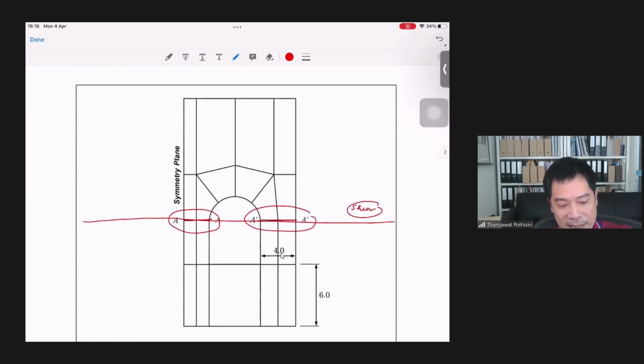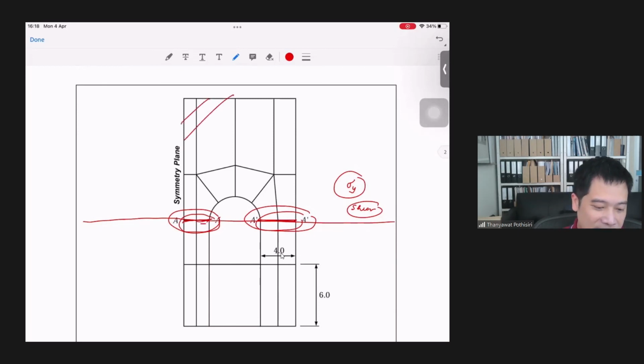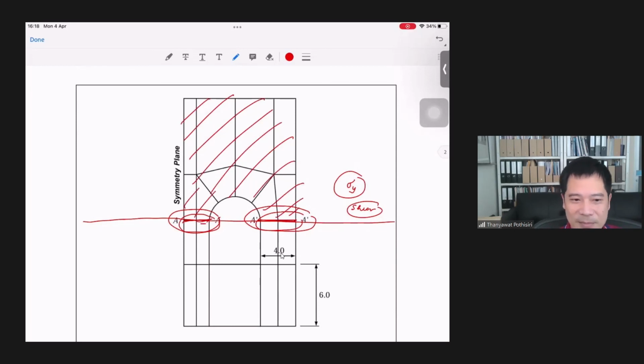So if you take a look at this free body diagram that results from cutting this structure, this plane, then you should draw certain conclusions based on this. Okay. What about sigma y? Along this plane, now you compute the resultant force based on this sigma y along this plane. You should see that this force should balance with the self weight of this portion, right? Something like that. Okay.